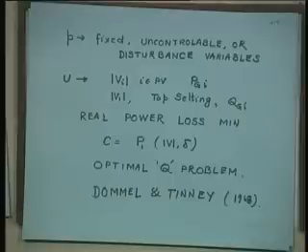Tap setting is also a candidate for a control variable, either on-load tap changing or phase shifting, which can eventually control the real power, and these taps will change the voltage, and so reactive power will be changed. That is QGi, which is again a control variable.